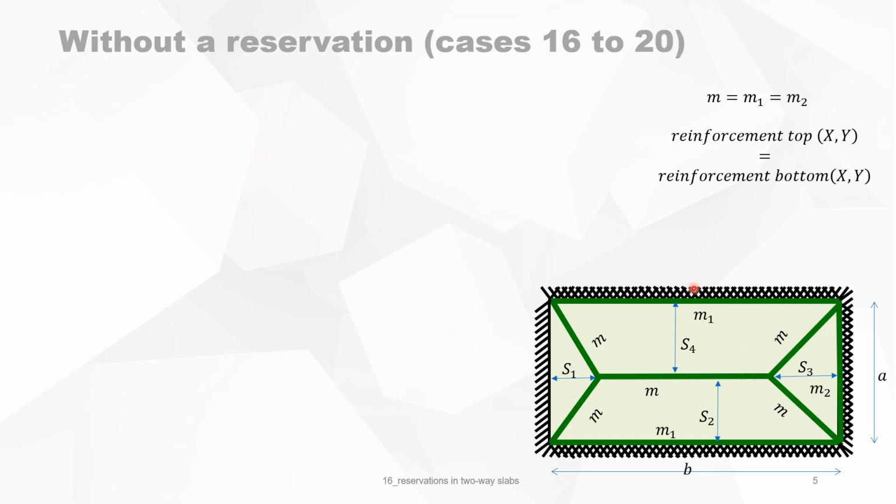But if you want to do it otherwise, we can always give this a different bending moment. The slab will behave like it is reinforced. So if we say this, for instance, is 1.5 M, and it is also 1.5 M, then if you put the right reinforcement, that will look like that. But for ease of working, we take M1 equal to M2 equal to M.